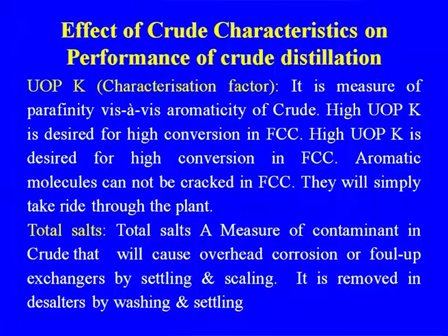Total salts will cause overhead corrosion and fouling of the exchangers, by settling or scaling. So, they are removed in the desalter by washing and settling. The knowledge of the total salt amount matters: if the salt content is higher, then the operation of the desalter has to be more severe. Severe does not mean temperature, it means more effective removal of the impurity has to be there.